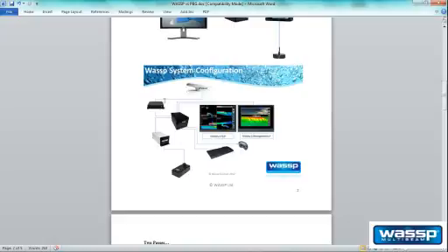So this satellite compass system compensates for the vessel movement as it pitches and rolls around, pitch, roll and heave. And then we have two display monitors, and here we have our acoustic information, which is our real-time information we looked at before, as well as our mapping capability. So WASSP is really a sounder and a mapping profiler all in one.